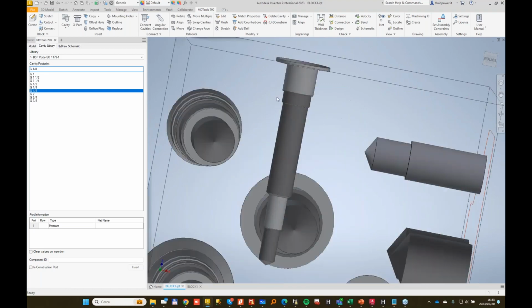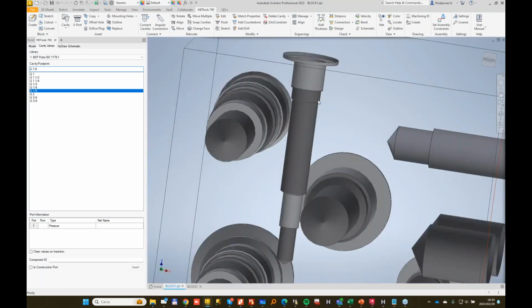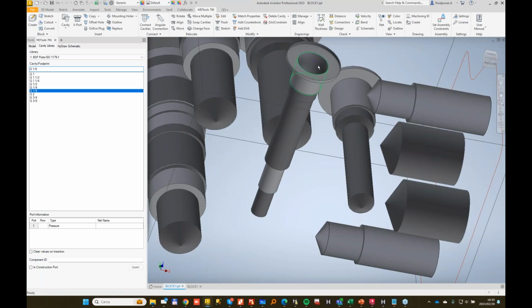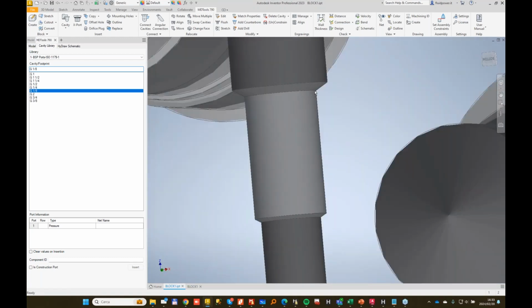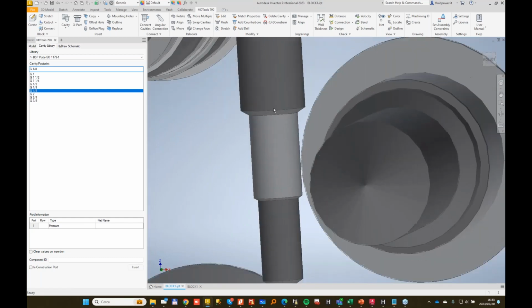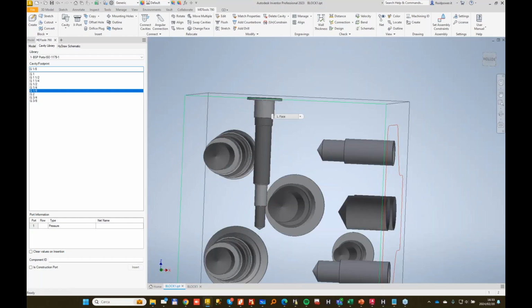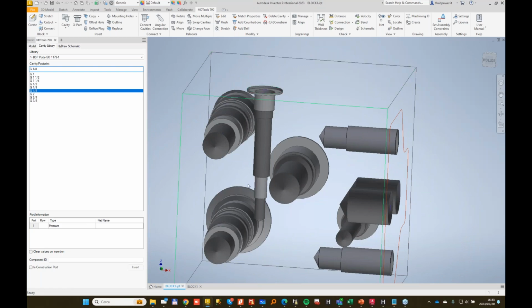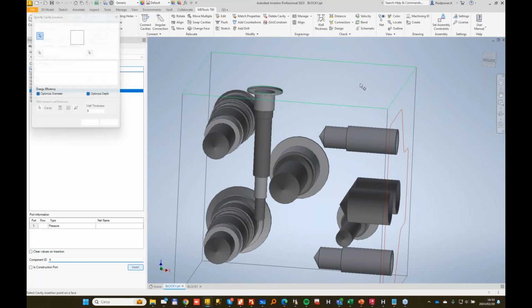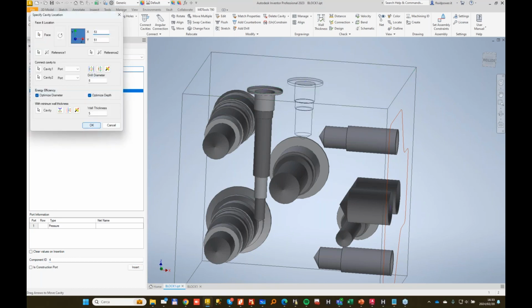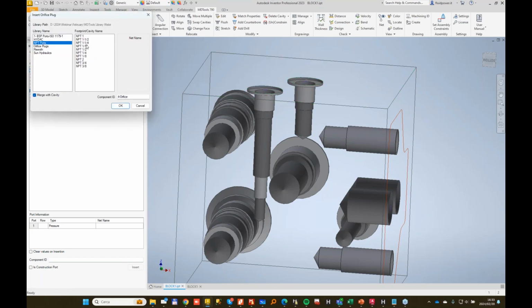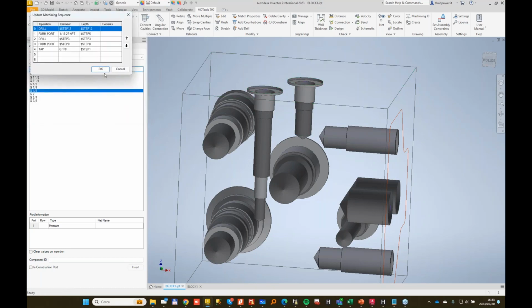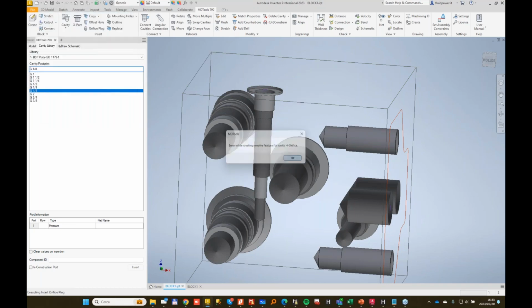This may not always be so precise, and this is something that I notice in the machining drawing, because since the drill is added at the end of the chamfer, the dimension is not always precise. There are also some decimal places which I don't like. So sometimes I need to fix it manually. But recently I discovered another problem with the NPT ports. So if you try with a small diameter to add an NPT 1/16, which is pretty common as an orifice, then there will be a cavity failure.